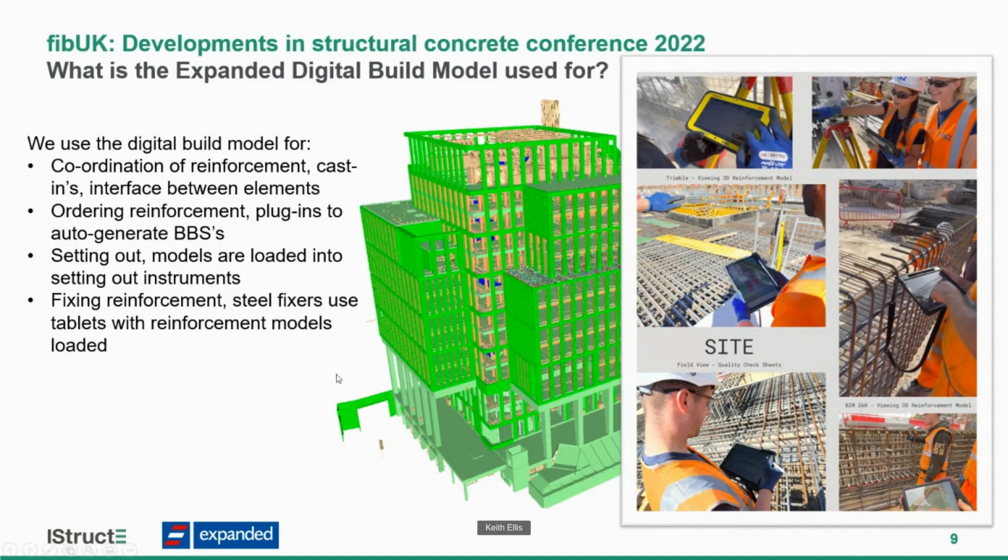The model was also used for setting out, so the engineers had imported the models into their setting out instruments, and they could set out directly and visually from the model. They're not having to take dimensions off drawings. And steel fixing as well, fixed from the model. It took a while, give them a couple of months with the tablet, they're all a bit pessimistic, but after a couple of months, you couldn't get the tablets off them. They loved it, especially in particular areas where the steel was very complex. They loved being able to move around in the model and see what was going on.